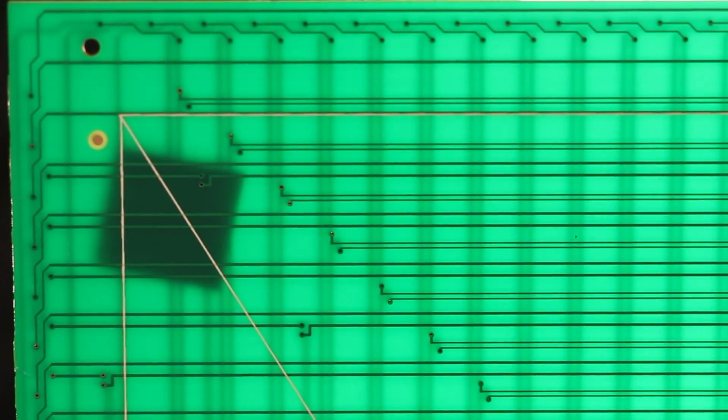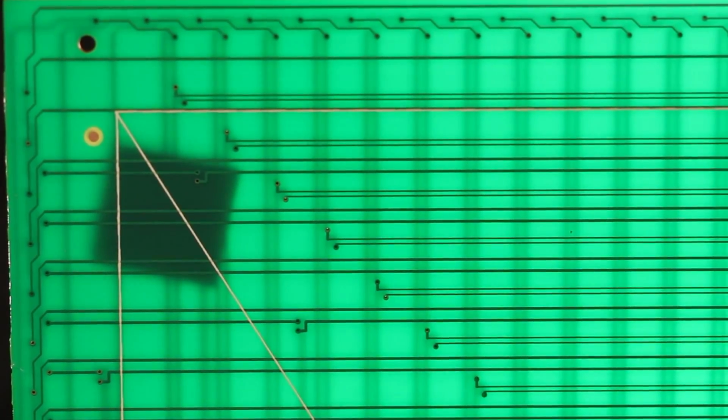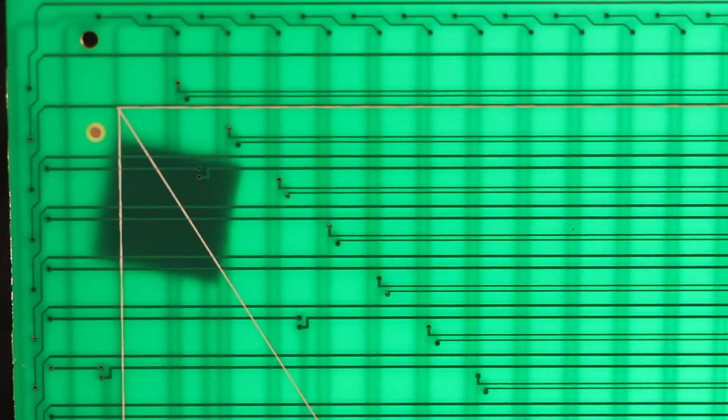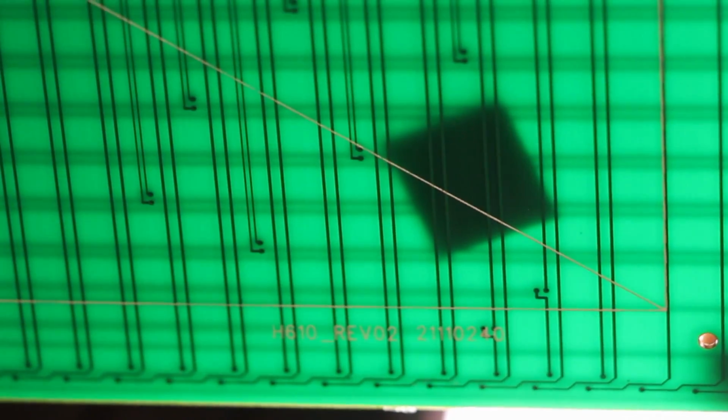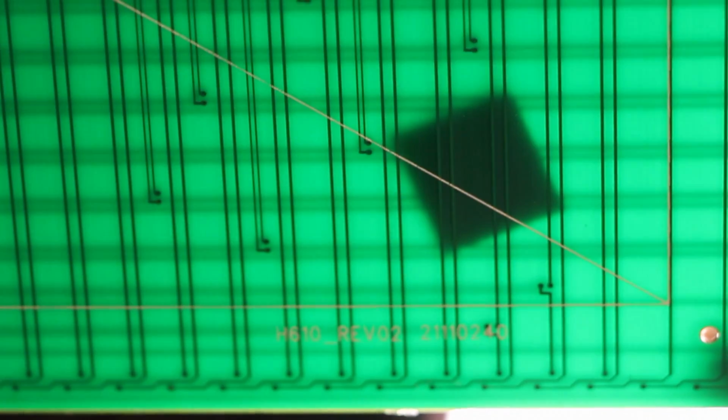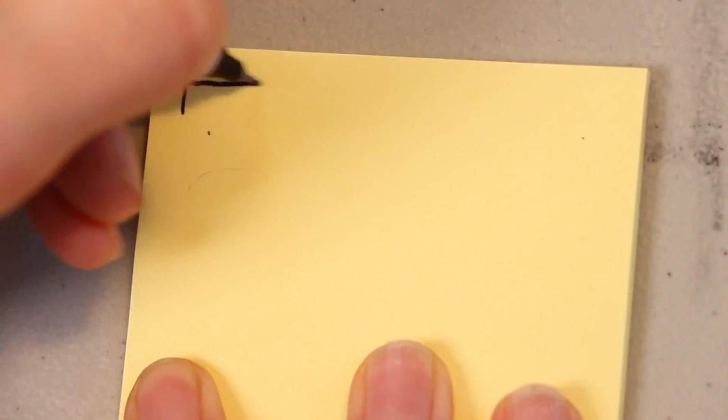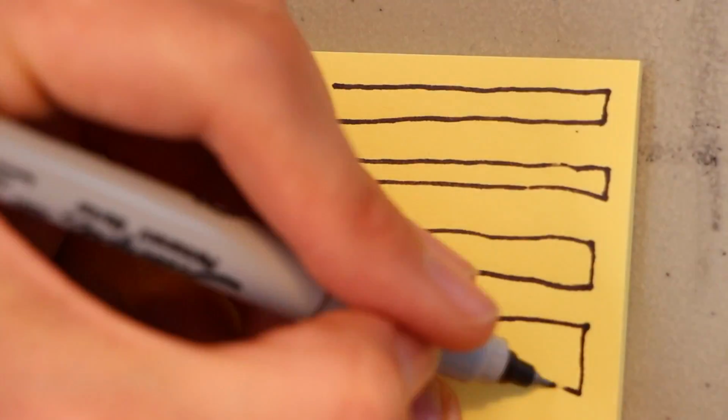Tablets use the printed circuit board itself in order to form an array of coils to receive the magnetic signal from the stylus. This tablet has a 2-layer circuit board, but it's been designed carefully, one array of vertical coils along the front side of the board, and another array of horizontal coils along the back side.